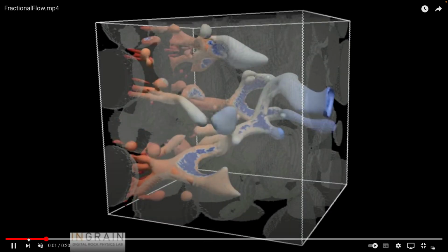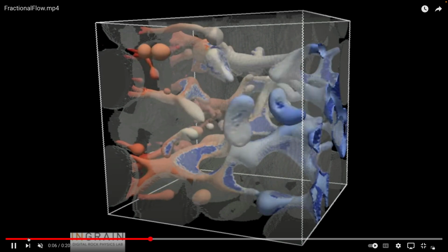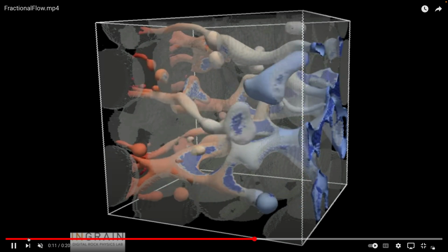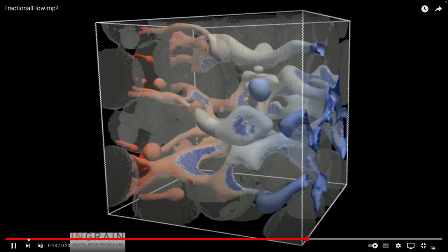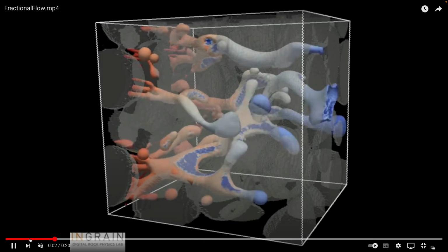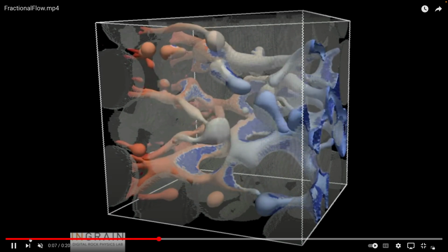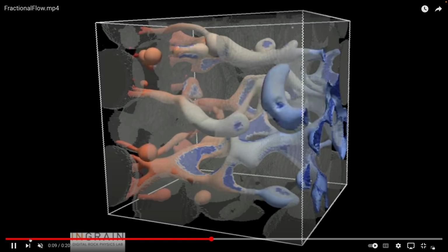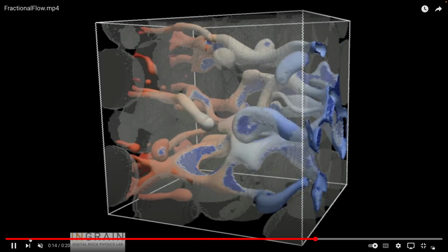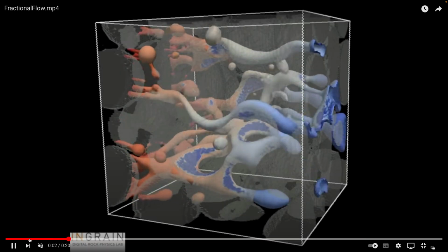So all these things have a reason. We're talking about thermodynamics and energy. We've made the case that what it does for us now is in two things. It changes our Bernoulli equation so that there are head losses and head inputs, energy inputs and energy losses in the system. And I made the case that, say, for flow in pipes and flow in porous media, which is what this is, the essence of the flow is the drag that's placed on the flowing water by the viscosity of the fluid as it flows past the grains.